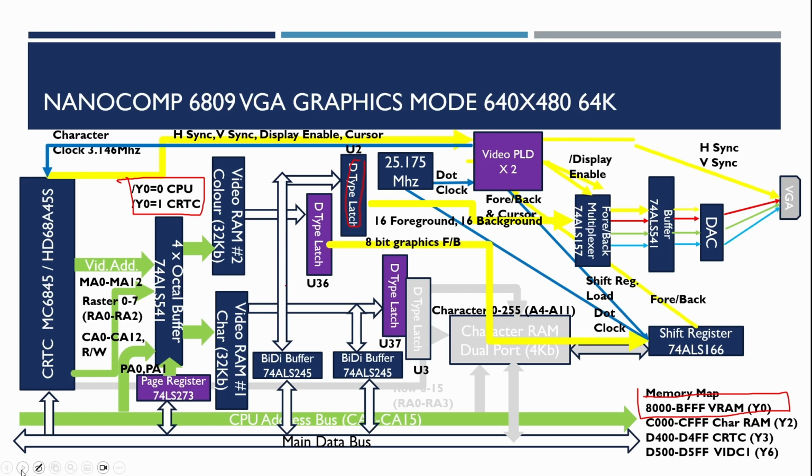So then if we look at where the data is coming from, the 8-bit foreground, background values are coming out of each of these latches, going to the shift register, and then determining whether we show the foreground or background colors, much like we did with the character generator output. So that was then using the same video digital analog converter that we used before. So then we went on to extend this to do the high color graphics.